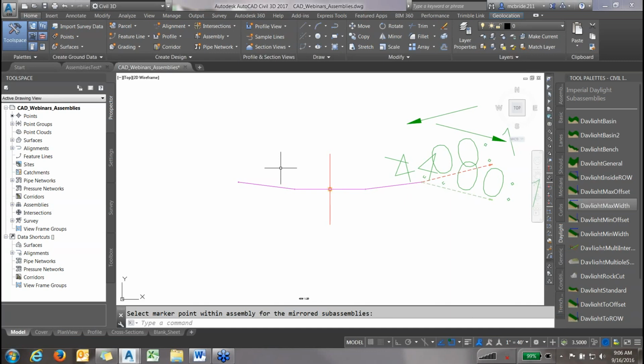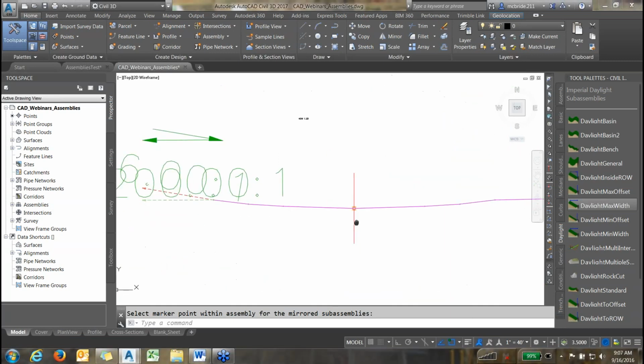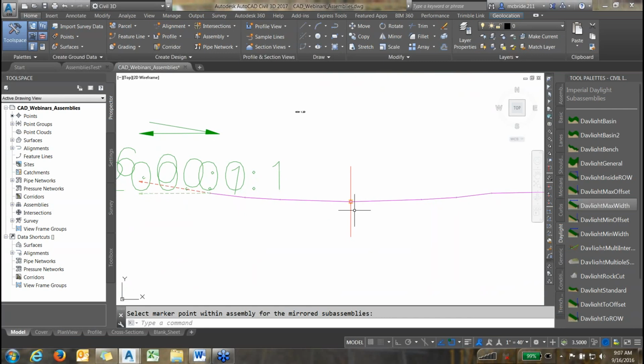So it's very similar. The reason I had to do a few more for the parabolic section was, if you're familiar with the standard, we have to do a 7-point check on parabolics. Okay, you have to check the center point, and you have to check the halfway widths, which would be about right here and right there. Then you have to check the 3/4 widths, which is right there and right there. Then you have to check the full widths.